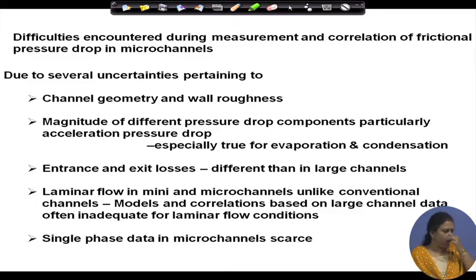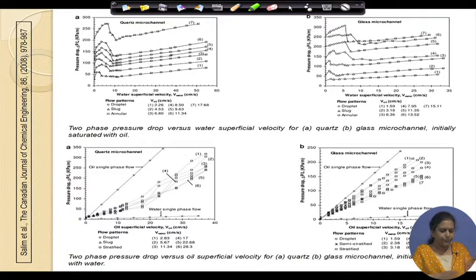And the other thing which I have already mentioned is that usually in this particular case it is laminar flow, but the correlations and models which are based on large channel data are often inadequate for laminar flow conditions, because in conventional systems, in practical situations, we hardly come across laminar flow conditions.